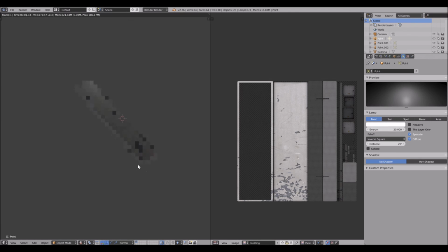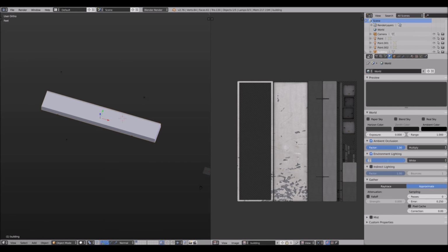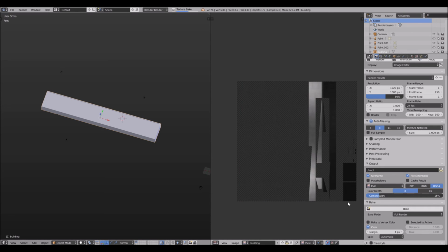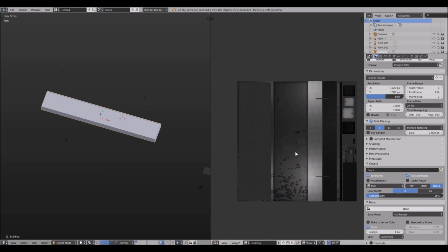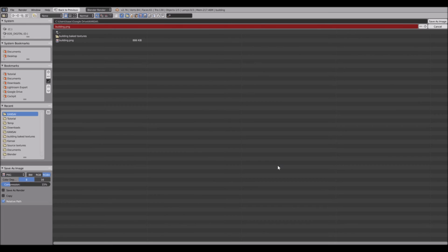There we go. And I'll select this, change the environment lighting down because it's night, put like 0.01, and then click bake. Then we have a light map that we can use that looks like the buildings at night. F3, and I'm going to add to the end of it underscore and then light map,